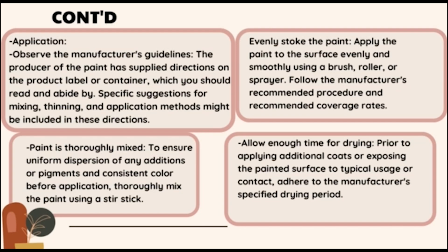Evenly stroke the paint, which is we have to apply the paint to the surface evenly and smoothly using a brush, roller, or sprayer. Follow the manufacturer's recommended procedure and recommended coverage rates. Next, we have to allow enough time for drying. This is prior to applying additional coats or exposing the painted surface to typical usage or contact. Adhere to the manufacturer's specified drying period.